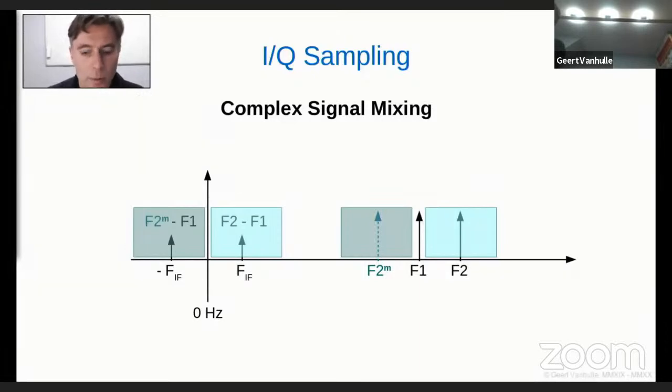So now we don't really need this sharp filter to filter out the mirror frequencies. As a matter of fact, all we need to do now is to filter the bandwidth around this f1 that is depending on the sample frequency that we are going to use in our baseband sampling. This will become a little bit more clear in the next slides also.